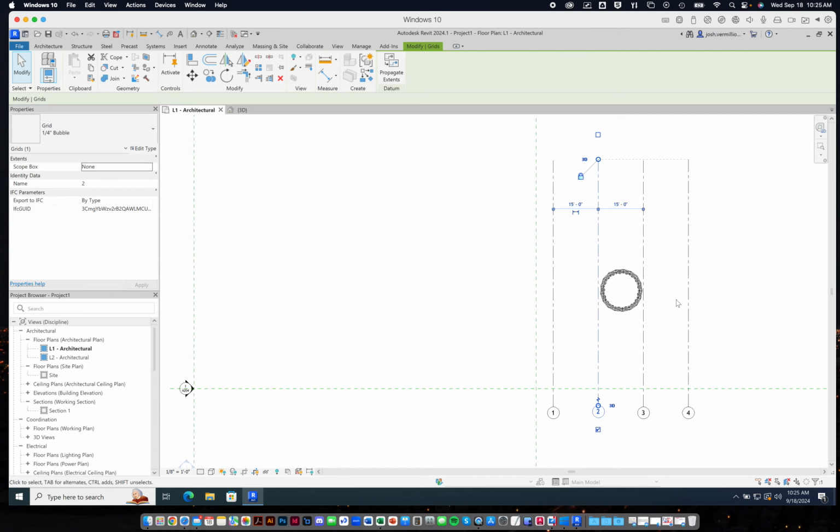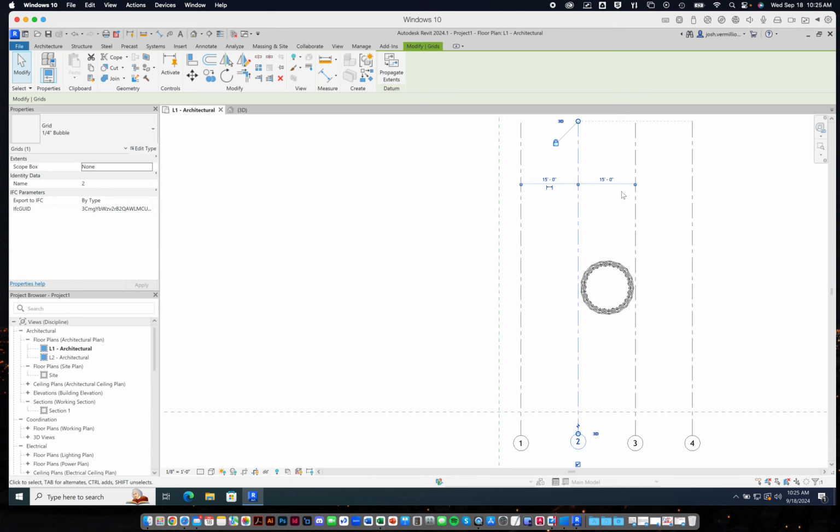And that's what's really nice about this. Again, it's parametric, just like Grasshopper, in the way you can begin to build relationships between things, right? In fact, when we do that, we'll start to build columns and beams. They'll be dependent on the column lines that we snap to. So if we move the column lines, then the columns and beams will adjust accordingly. All right, so once again, I'm still in grids.